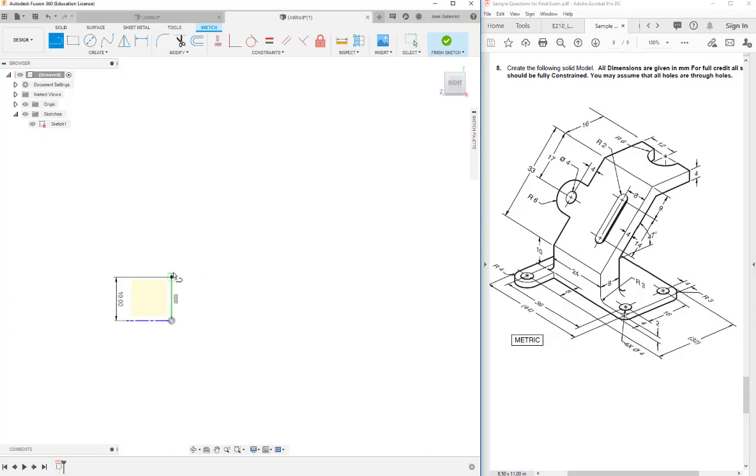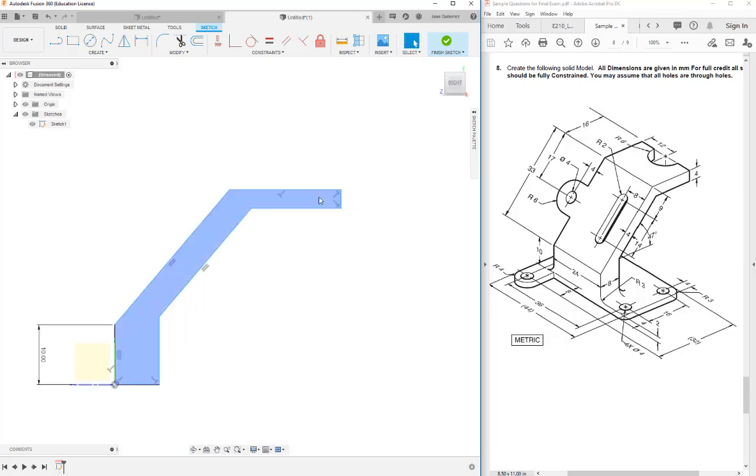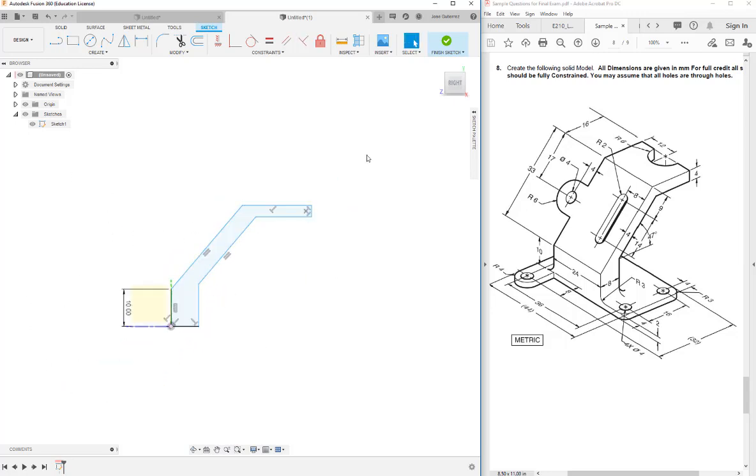Okay, so I'm going to continue working around. And I could probably use the offset tool. That might be a good tool to use. As I drag over here, I've actually allowed it to be parallel. We see that it is parallel. I can hover over this and get a snap. And if I double click, that ends my line tool. So I didn't quite get all the geometric constraints. Those are the ones we'll work on first before we add the dimensions. But now it looks like I have all the geometric constraints in place. That was by design as I used the line tool.